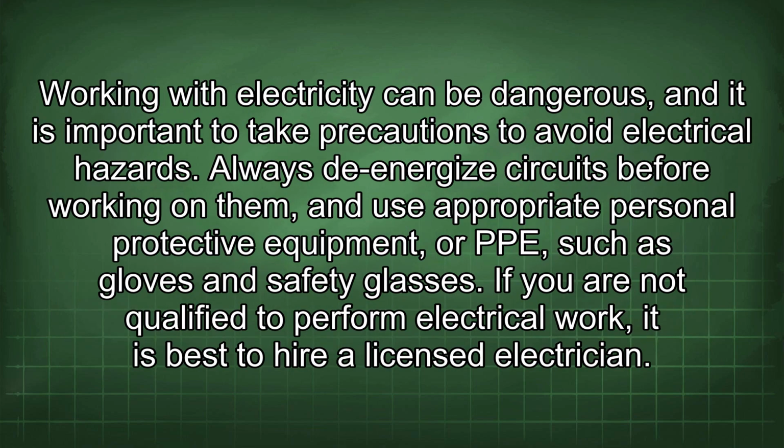Working with electricity can be dangerous, and it is important to take precautions to avoid electrical hazards. Always de-energize circuits before working on them and use appropriate personal protective equipment, or PPE, such as gloves and safety glasses. If you are not qualified to perform electrical work, it is best to hire a licensed electrician.